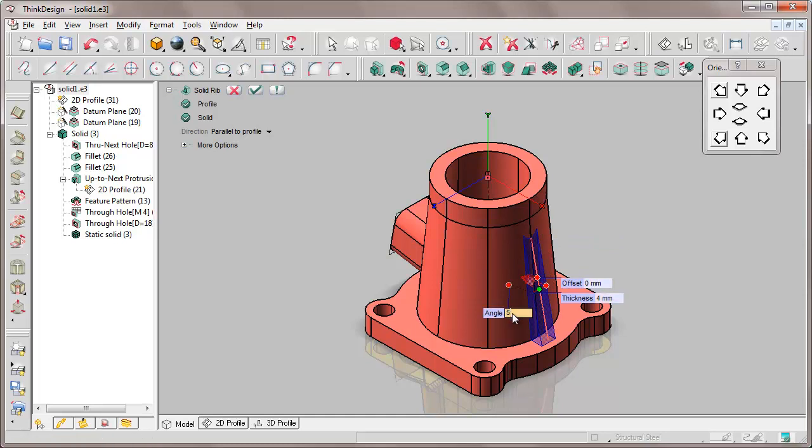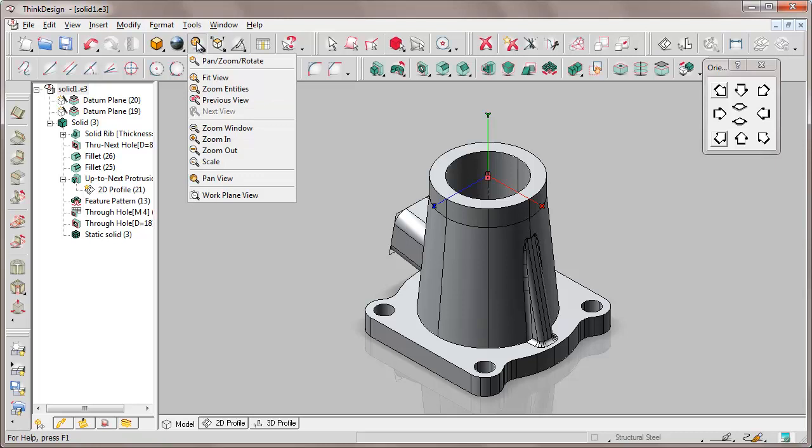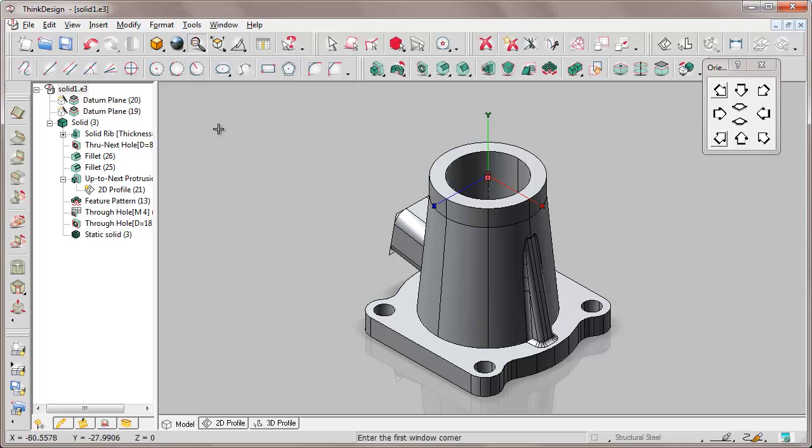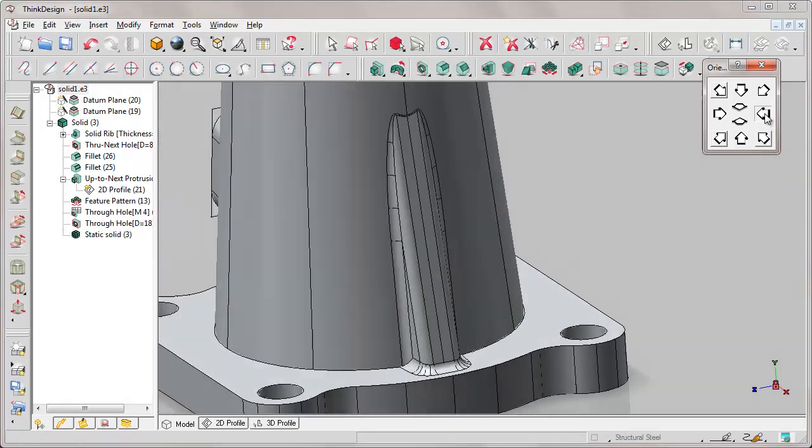In other options, we specify a base radius of 1 mm and a common radius among all the resulting edges of 1 mm. In actual fact, here we have completed our job, that is the first project specifications requiring to make a solid with a rib, a protrusion, and a hole.